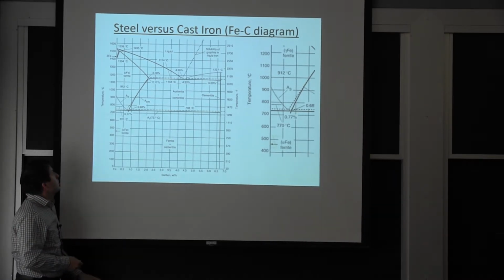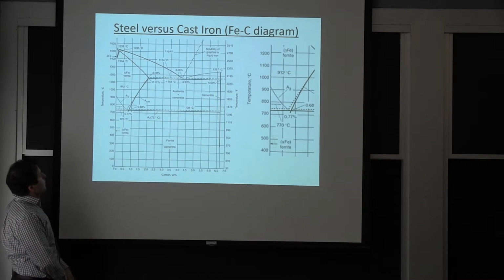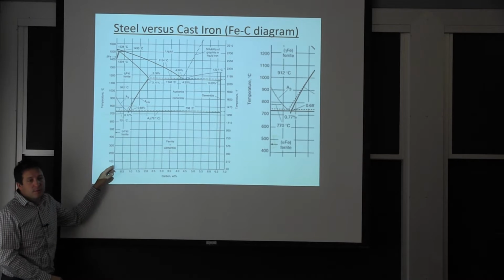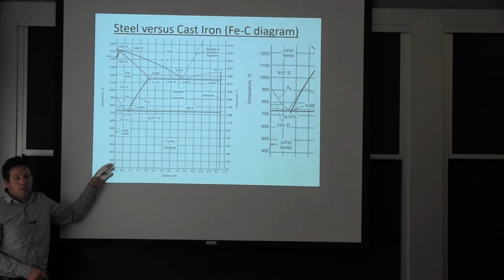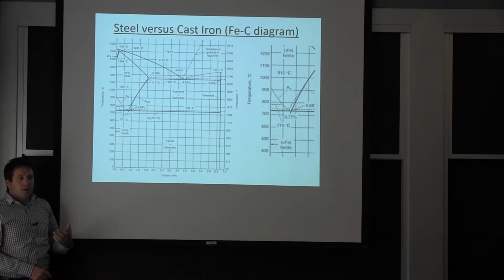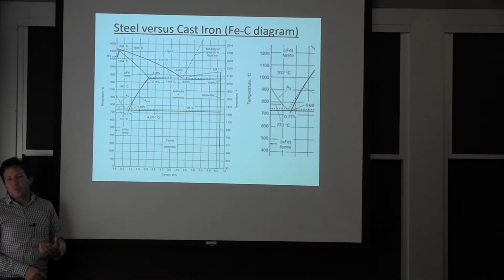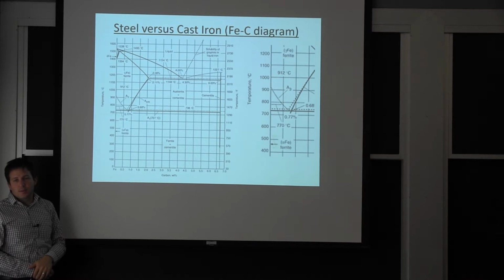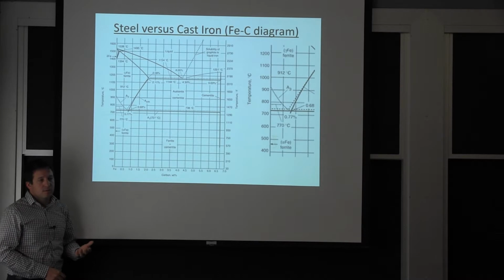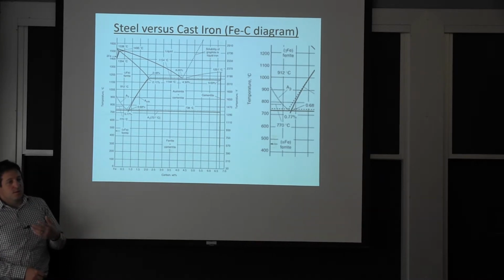So the most typical one for structural steel, the largest volume, is somewhere around 0.2% carbon. And you will go higher, maybe if we're thinking about a fairly high-strength steel for a heat treatment, it's going to be around 0.45% carbon. And that would be a steel used for landing gears on aircraft. It goes through this whole process of quenching and tempering to reach a combination of strength and toughness.